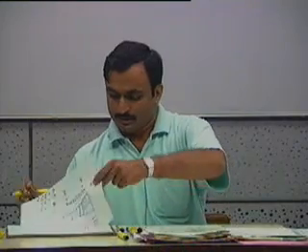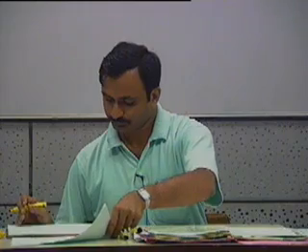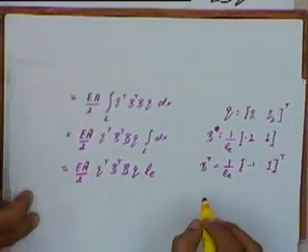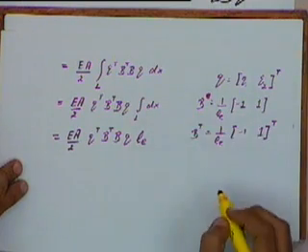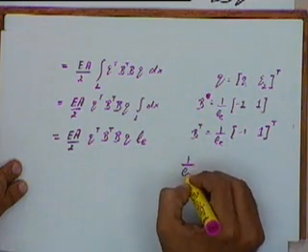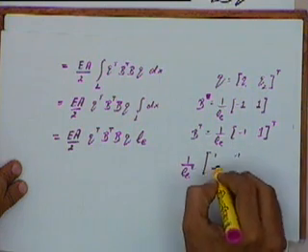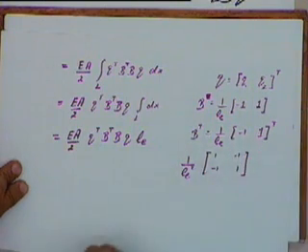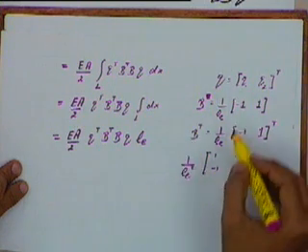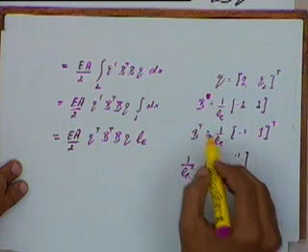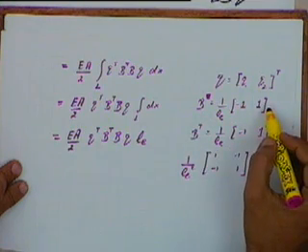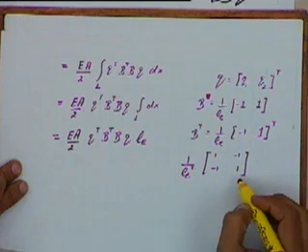So this is what we get. Now B transpose into B. If I multiply these two matrices, I will get 1 over LE squared multiplied by 1 minus 1 minus 1 1. B transpose is a column vector of size 2, B is a row vector of size 2. If I multiply the two, I will get a 2 by 2 matrix.